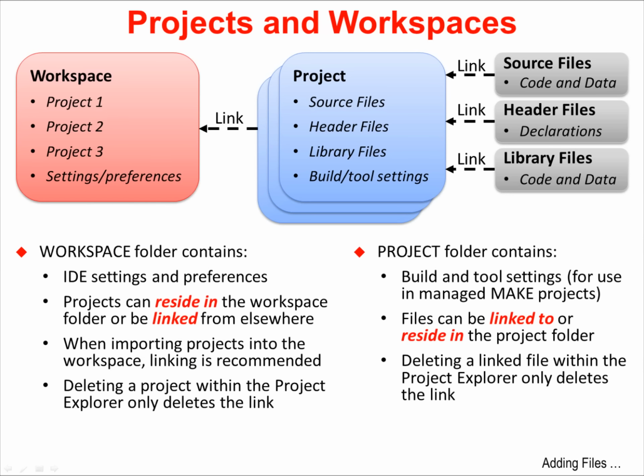This is a conceptual view of workspaces and projects. Physically, both of these are merely folders on your computer. The Workspace folder contains Code Composer settings and preferences. Projects can either reside inside the Workspace folder or can be linked from elsewhere. When you delete a linked project using Project Explorer, only the link will be deleted. When you delete a copied project using Project Explorer, the actual project will be deleted.